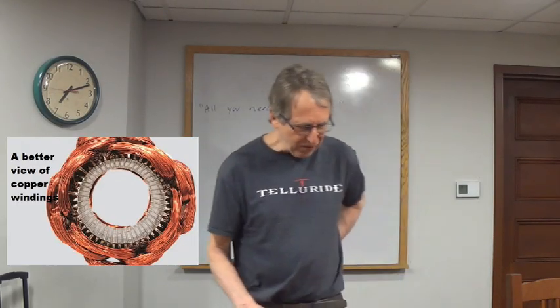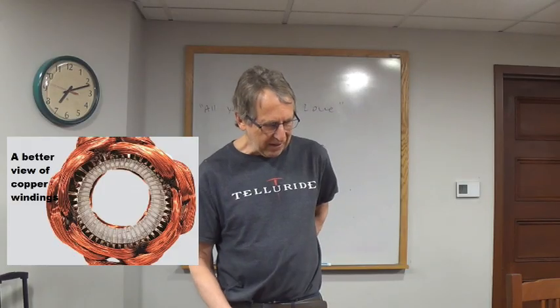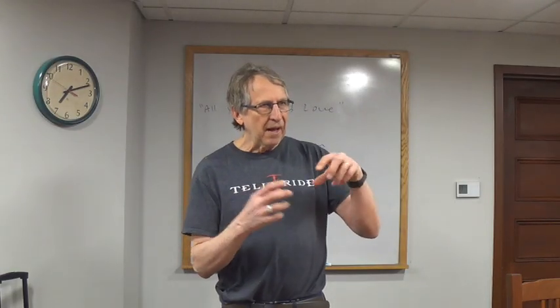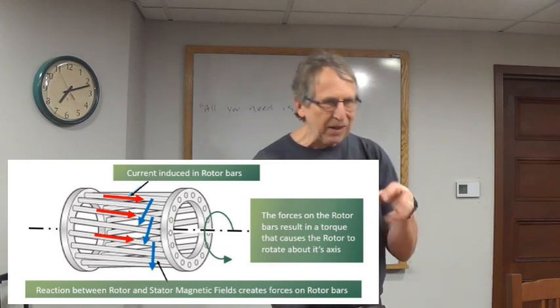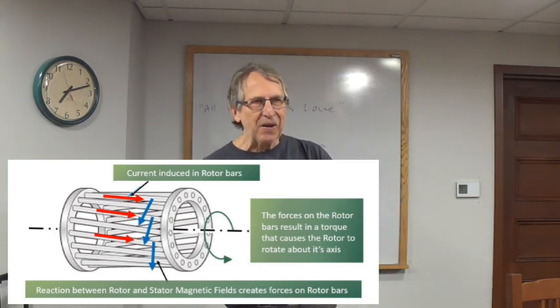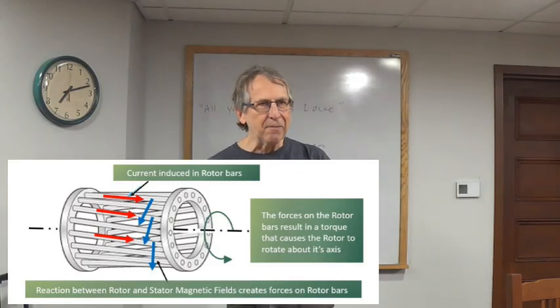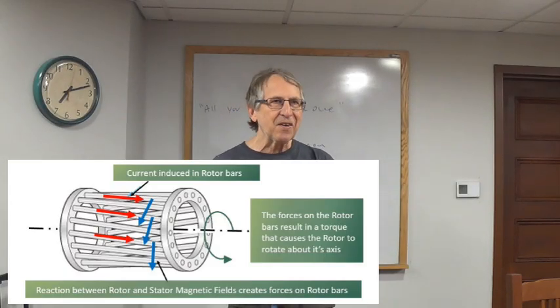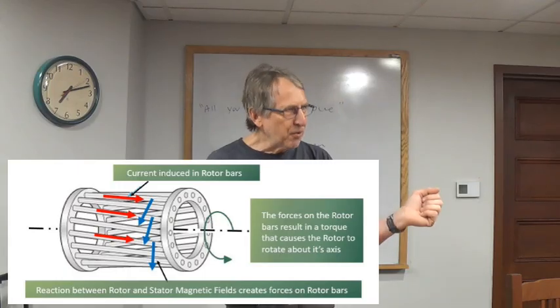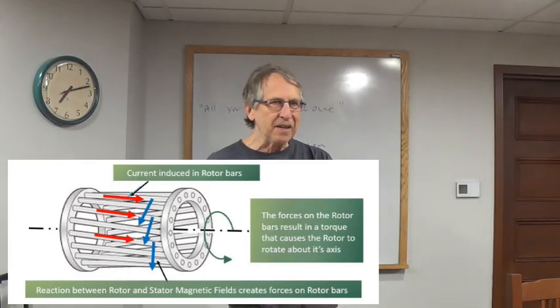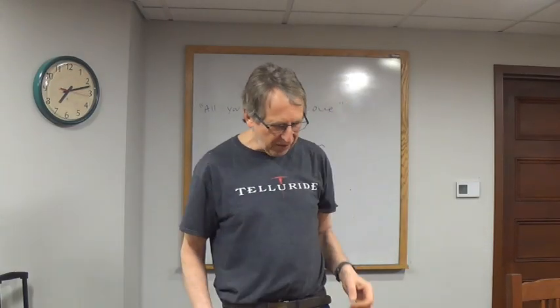It's kind of a clever trick that Nikola Tesla came up with. That cast aluminum thing is configured in such a way that when you subject it to a magnetic field, it generates its own opposite magnetic field. Because it induces a current. The current induces a magnetic field, but in the reverse direction. And so it's like two south poles pushing apart. And so the rotor tries to get away and begins to turn. That's clever, interesting.